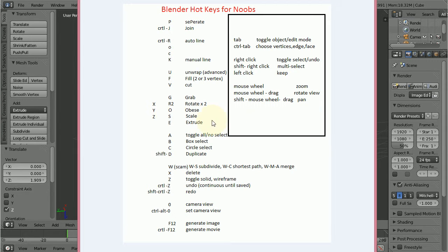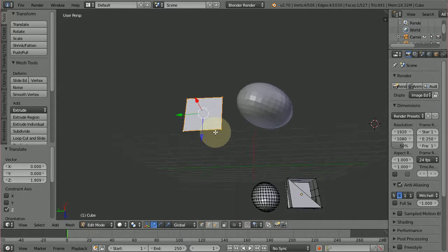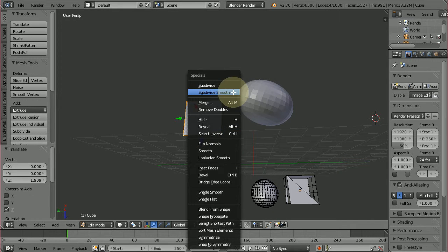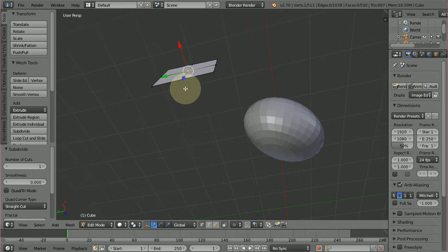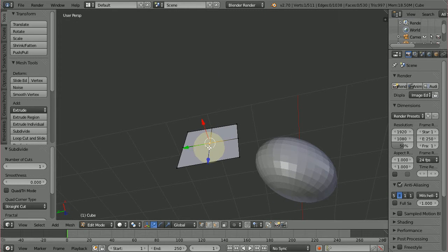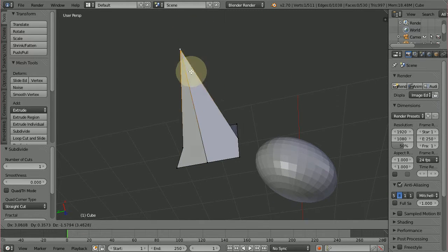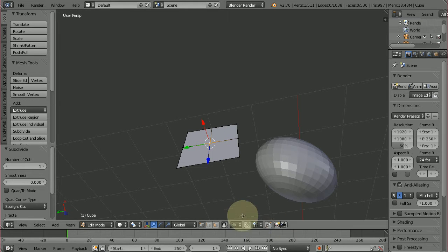Okay. Proportional editing mode is quite interesting. I'm just going to subdivide this so I can show you. Say I wanted to make a mountain. G makes a peak. But in proportional editing mode, watch down here when I hit O. Let's just unselect. There. That shows up. If I hit O again, come on. Okay, let's leave it on.